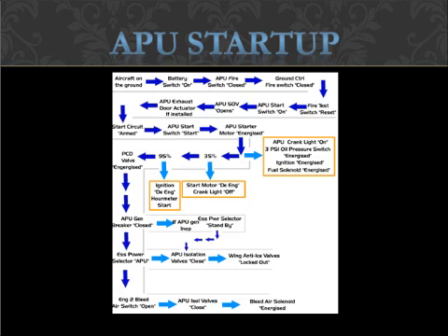More modern engines are becoming more electric machines. These APUs and main engine transformer rectifier units produce 400 Hz of alternating current power, so that smaller conductors are routed throughout the aircraft instead of insulated stainless ducts, which are very heavy.